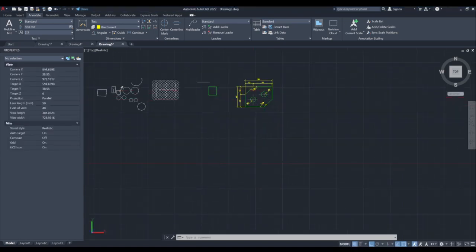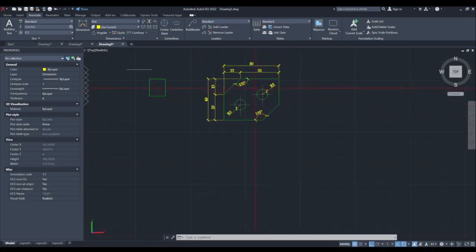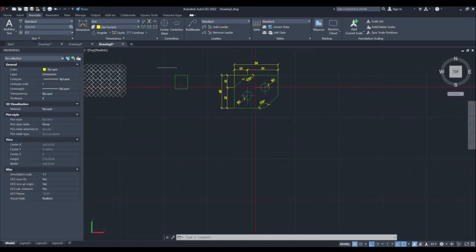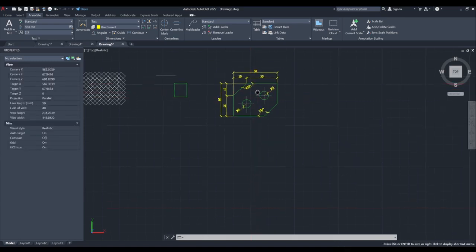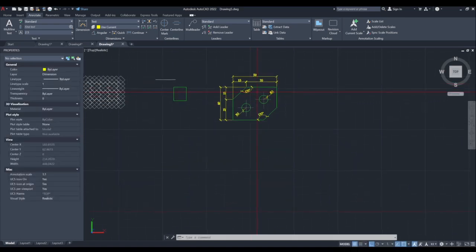So we discussed last time, in the face-to-face meeting, the first angle projection and the third angle projection. The third angle projection is located at the third quadrant of the four quadrants of the work plane. So the top view of the object is in the third quadrant of the plane, while in the first angle projection, the object is on the first quadrant of the plane.